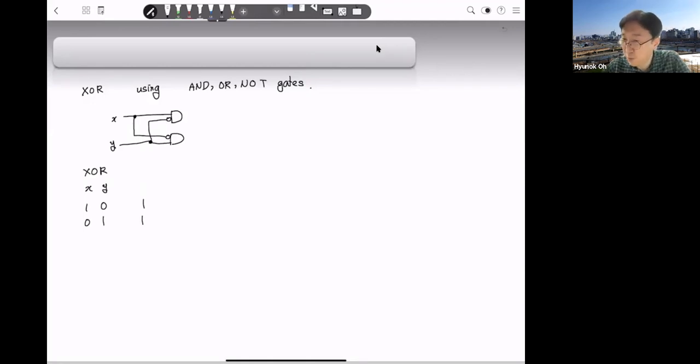So here, if we look at this gate, X is 1, Y equals 0 case. So this is 1. Then because of this NOT, it is 1, so the output is 1. In the lower case, it is 0, 0, and the output is 0. Okay, so we are combining these two inputs using the OR gate. Then it's 1. Input is 1, 0 case, output is 1.